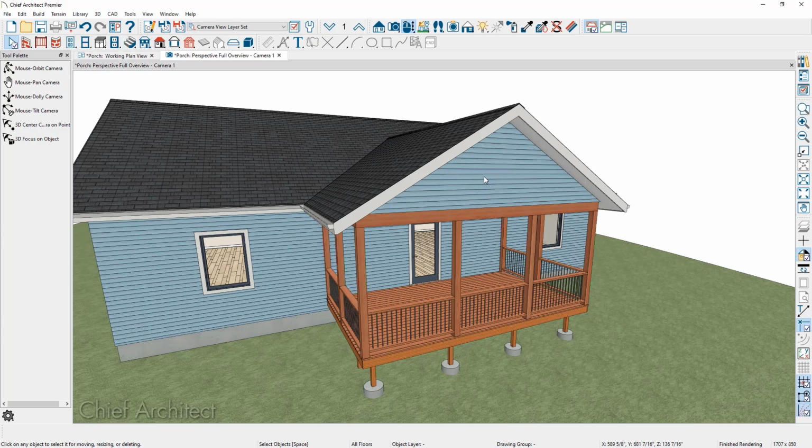For the purpose of this video, I'm fine with this attic wall, but if you did not want this attic wall, you could get into your default settings, and under the wall default settings, uncheck automatically rebuild attic walls, and then select this attic wall and delete it, and then proceed to design what you would like in this space using the 3D Solid tools.